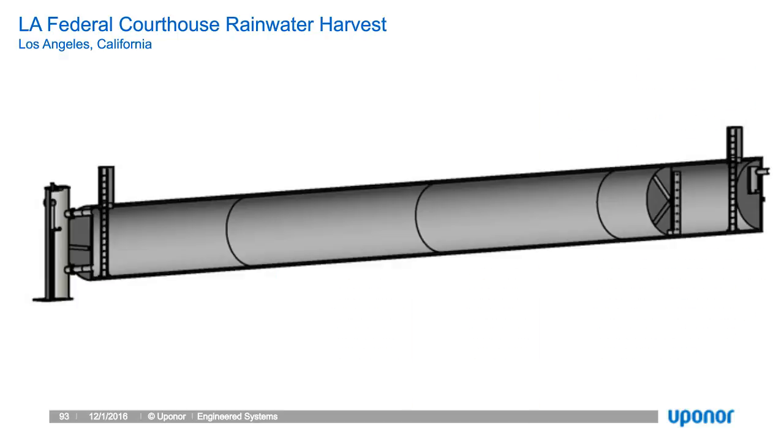Here you can see an actual isometric of the structure. This was actually 4 11-foot diameter sections that were delivered to the project, and then field extrusion welded to create a 100% watertight system. On this project, it's also interesting to note that we provided a submersible pump station, a standalone vertical submersible pump station, to remove the submergence depth requirement for the pumps from the vessel itself.